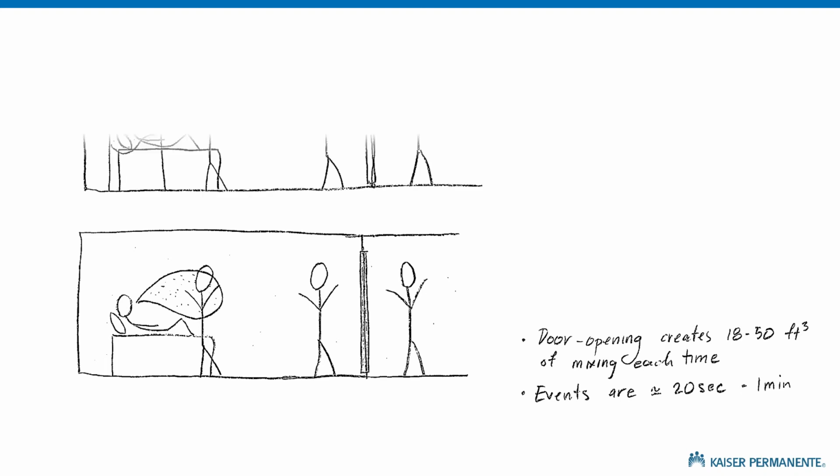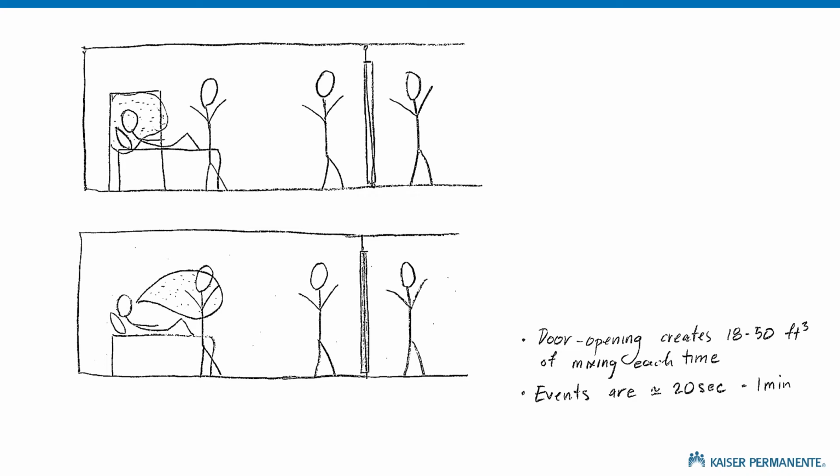The single biggest idea we've seen this year is this one. It's called the ventilated headboard, and I'll show you some pictures of this later. But think of it like putting a kitchen hood right over the patient's head to catch those aerosols before they become part of the room air. That's a great idea, because if we can catch 80 or 90% of those particles and prevent them from mixing in the room, that changes the math, and it changes the math a lot.